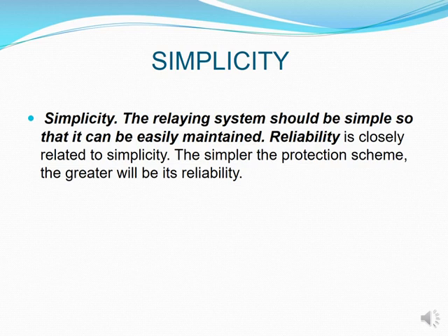If your protection scheme is complicated, with too many conditions saying if this happens then this must go, if that happens then that must happen, then you have a huge chance of errors and your relays tripping when there is no actual fault or no need for them to trip, and therefore they become very complicated.